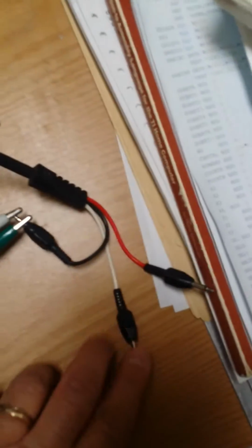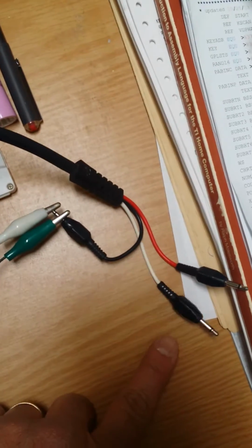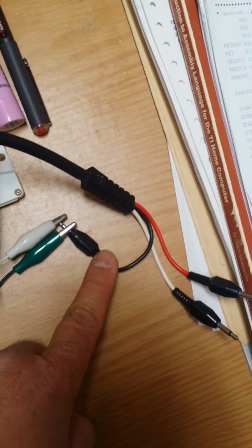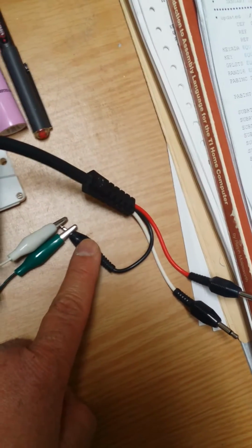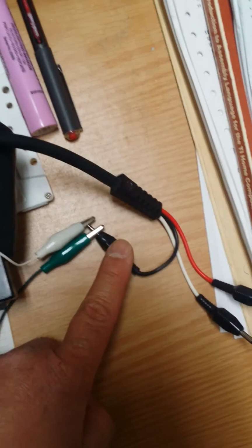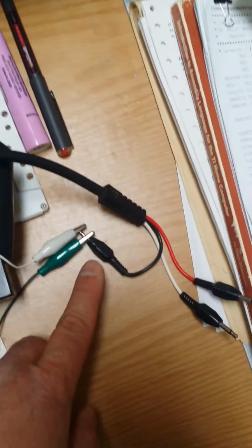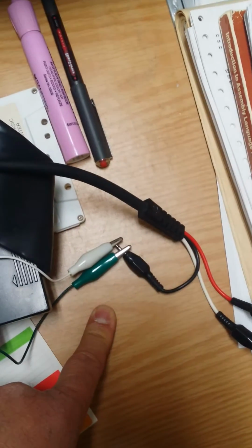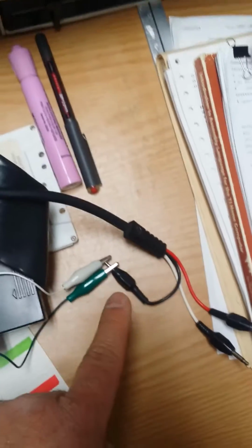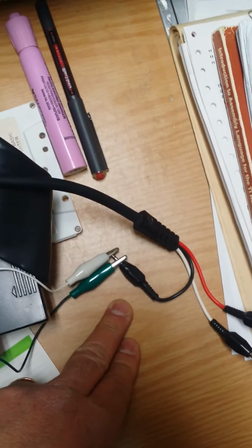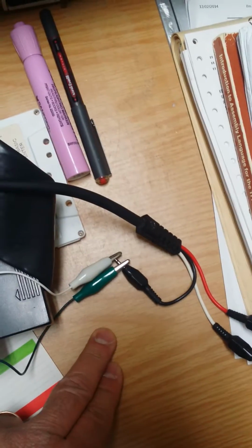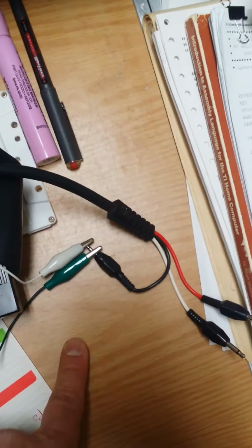These leads here lead to the mic and to the ear jacks on your usual cassette recorder. This jack here is the remote jack, which controls the motors on the cassette deck. And this is what we're going to use to trigger the igniter. What this does is, once it is triggered by the computer, it essentially closes a circuit and acts as a switch. Basically it connects these two leads together.